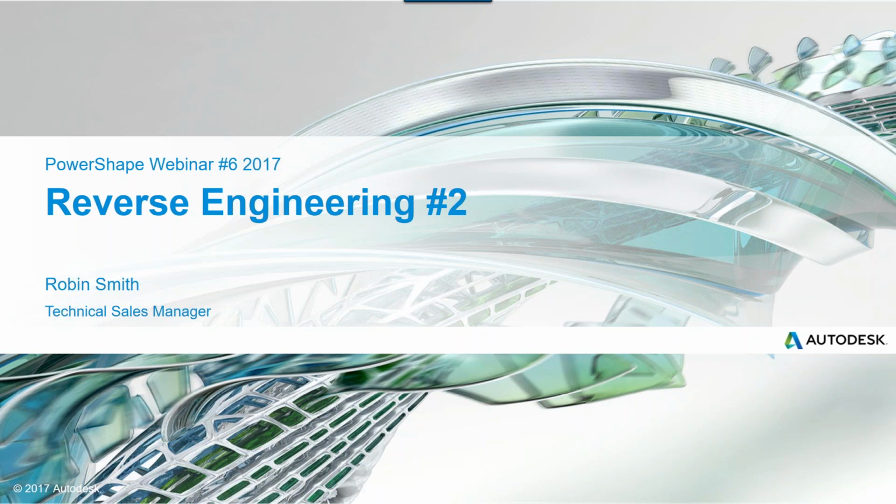Now, in a previous session, I covered other reverse engineering techniques, such as triangle model registration, how to align different triangle sets together when they're not in the same coordinate system, how to triangulate over point clouds and the best practices there to get the best results for the triangle spacing. I also covered how to surface over a mesh, and there are many different strategies for doing that, using simple surfaces that are trimmed and untrimmed, shrink wrap surfaces, and the smart surfacer. All of that is in a previous session, which is available from the webinar website.